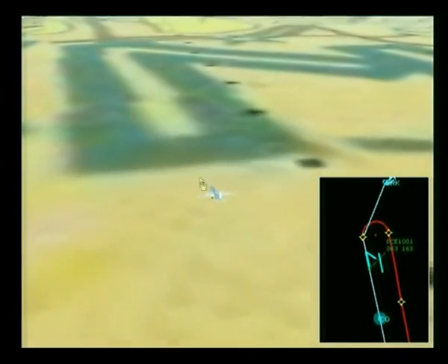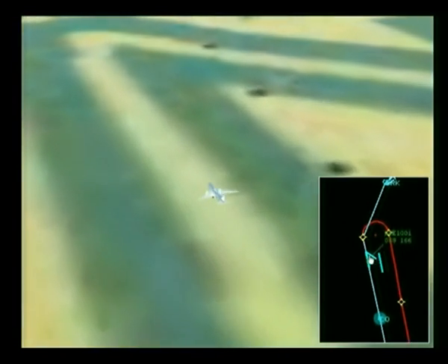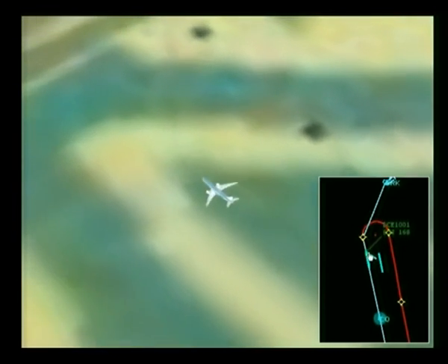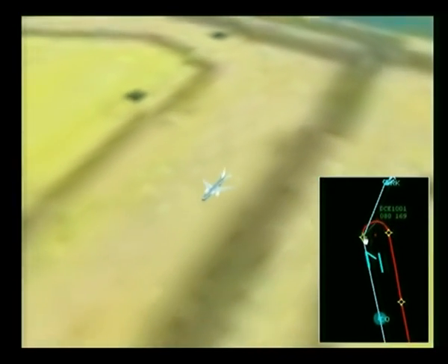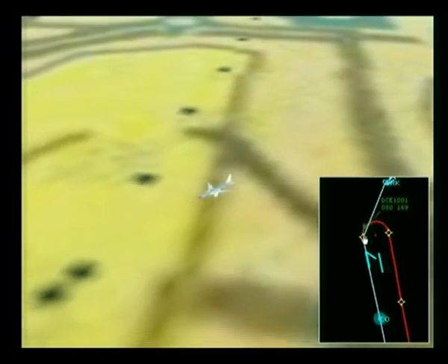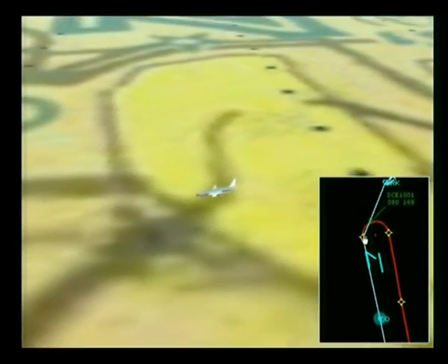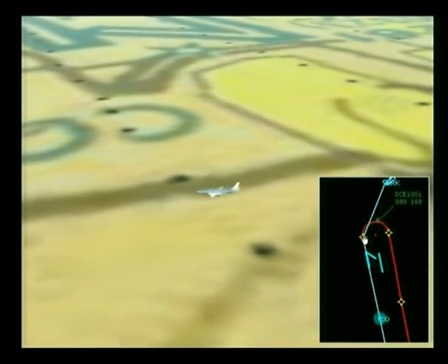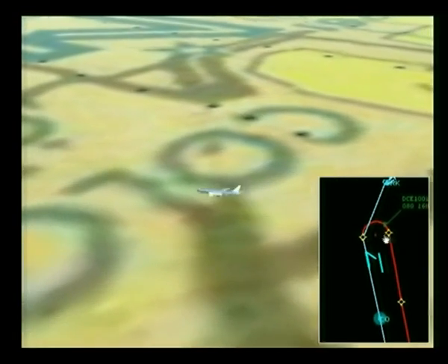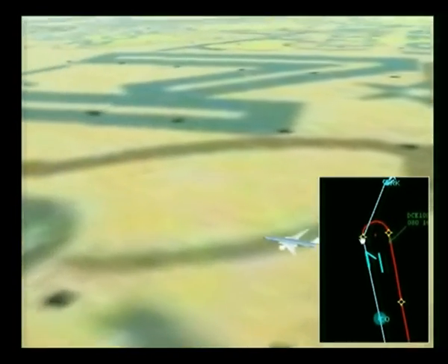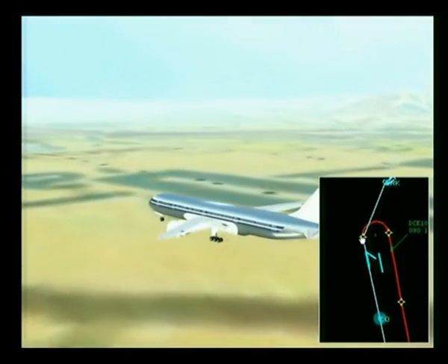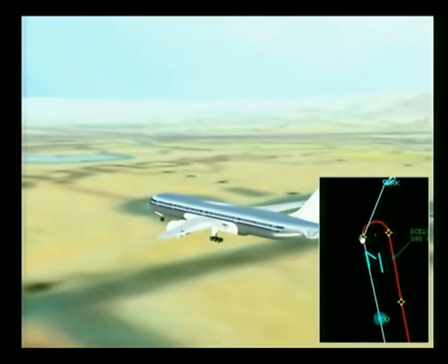You're going to see him hit the runway and commence the missed approach here. And then you're going to see the right turn at this waypoint. These can all be installed in the FMS, the waypoints and the misses. This whole engine out procedure can be conducted with this course guidance, in this case, hitting these waypoints, and on the autopilot. It makes it almost an effortless, no-brainer procedure for the...